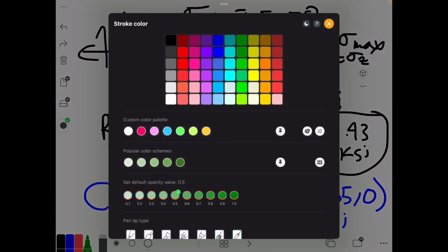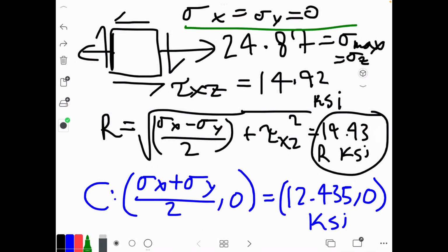As proven based on the last steps that we did, we're not going to have a stress in the x and we're not going to have a stress in the y. All going to be 0 because we didn't have anything for them. This is also because these stresses that we have, we are looking at H. H was on the top of this bracket. There is nothing really being added on the x. Remember that we did in the beginning, we didn't have a Cx. We didn't have any force in the x direction.